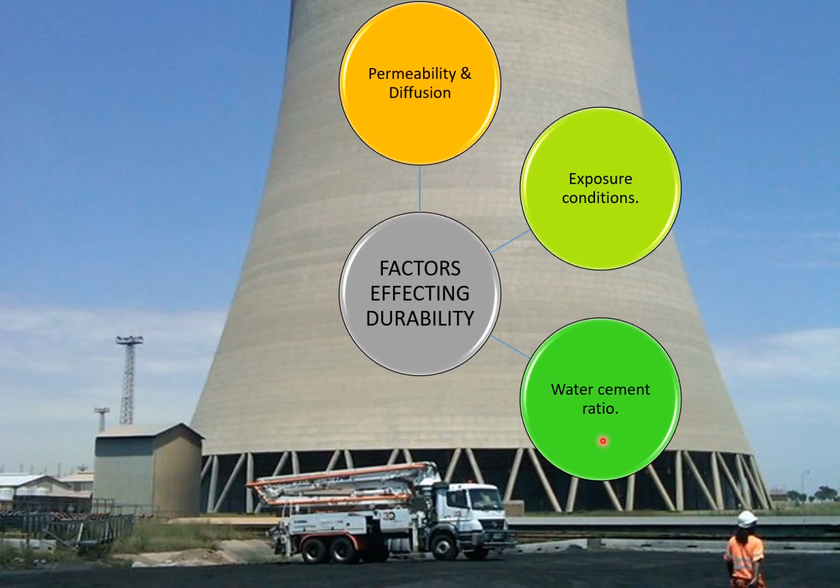So it is important that you maintain the water cement ratio stated in the standards, the maximum water cement ratio, and it should be as low as possible while still getting a concrete which can be easily mixed, placed, compacted, and finished for a particular member.